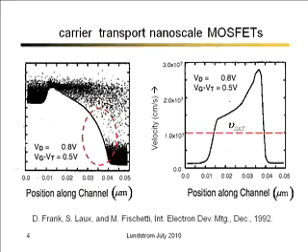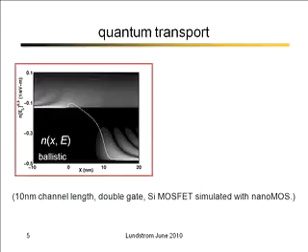And that's just a reflection of what can happen in a very short device where there isn't time for the scattering really to come to steady state and to equilibrium. The electrons are out the drain before they've had a chance to scatter enough for their velocity to saturate. So this is called off-equilibrium transport. You know, things get very complicated in these small devices. Now you can ask about quantum mechanics too. In these very small devices, you can ask whether we really should be thinking of these electrons as classical particles or should we be treating transport quantum